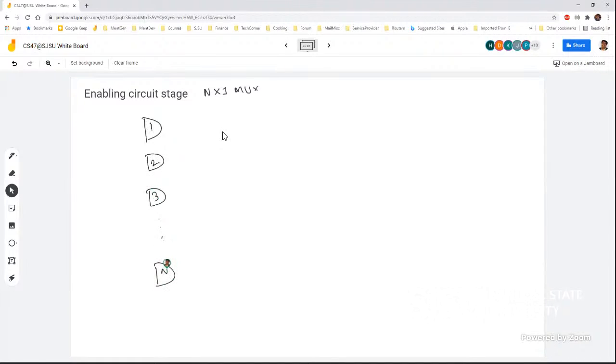So in this problem, we have 8x1 multiplexer. So definitely we have 8, and now the question becomes how many bits? We are talking about 4 bit here. That means each of these is basically 4 individual inputs to accommodate each bit.